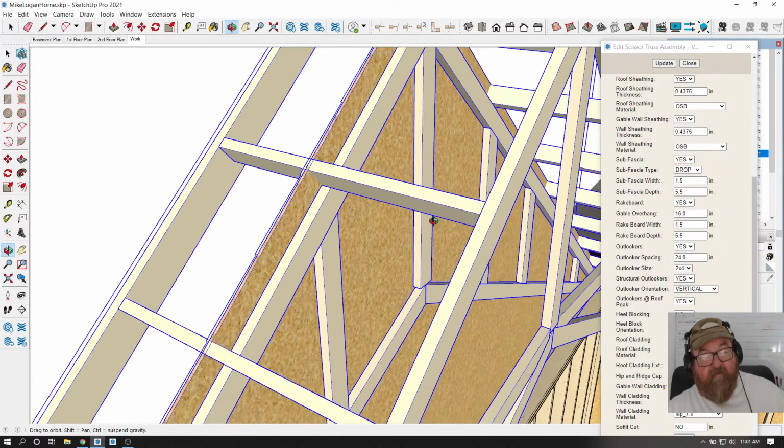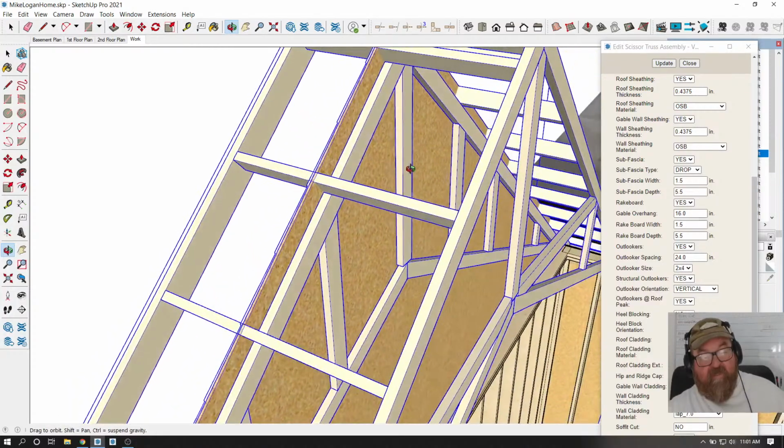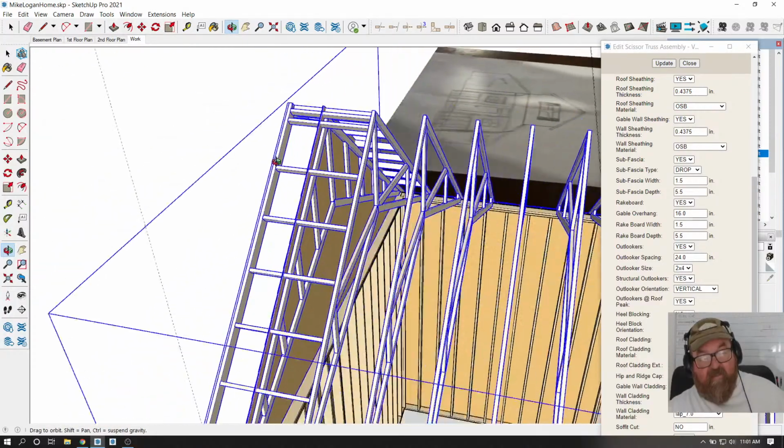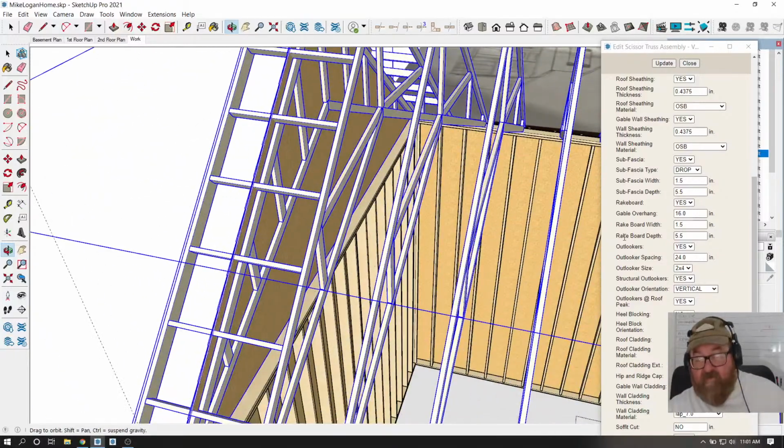in your drawing. Then you'll say, oh, I need to make a note. I want to drop the gable end truss. Okay, and that just makes it so much better. And you can get by with these on 4-foot center. You don't have to put them